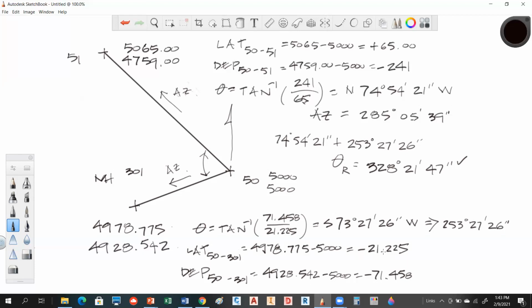So we would square that plus that squared, take the square root of those sums, and that'll give you the distance. Okay. So that's using inversing, but that process, we would call this process radial stakeout. Okay. So, I hope you guys are starting to appreciate there's a lot you can do with this. The more you do it, it gets easier. It does get easier.